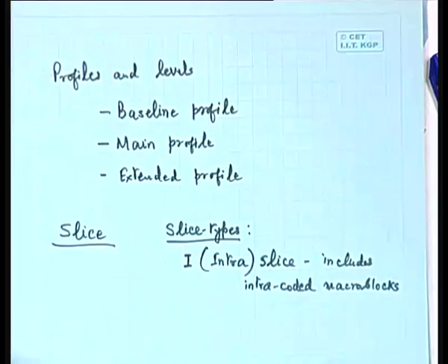Well, for a slice we can define a data structure, and a major advantage of using the slice is that we can give unequal importance to the different slices, like slices which correspond to the macro blocks in the foreground area, which are more important to us in the bit stream, as compared to slices which are not in the foreground area.